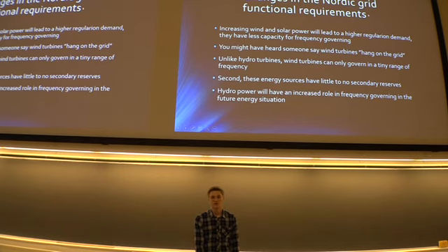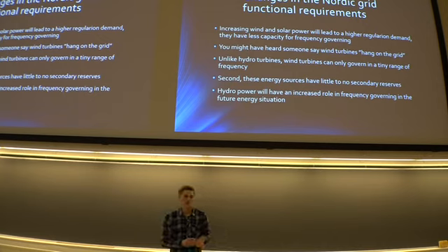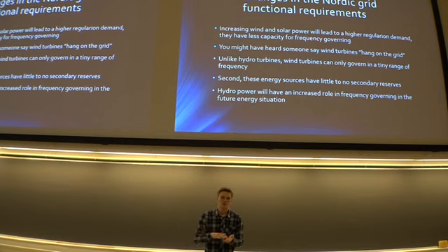So there are some changes in the grid functional requirements, which is partly due to an increase in low energy sources, which are low in secondary reserves, which means solar and wind, especially a lot in Europe. We are getting more connected. They don't have the potential like water power has. If the frequency drops, you have a big reservoir, you can just flood all the water into the system to boost this frequency back up.